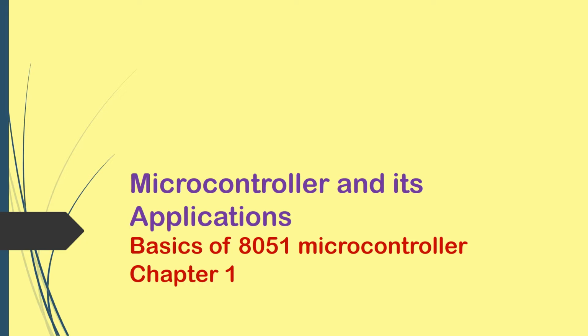Microcontroller design and hardware is comparatively low cost, whereas processors are comparatively expensive. Microcontrollers are very easy to replace, but processors are not that easy to replace. Microcontrollers are built with CMOS technology, which requires less power to operate. As far as microprocessors are considered, their power consumption is high because of n number of controls and the entire system they are supposed to control.